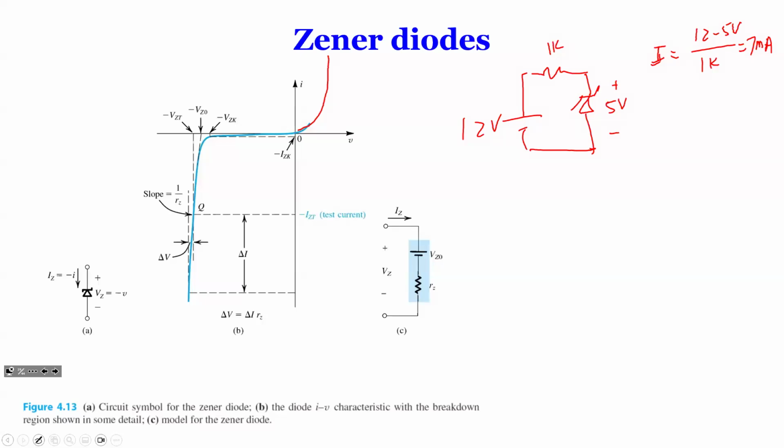As I mentioned earlier, if you look at the blue curve down below this X, it's not exactly constant. It actually changes when current increases. But again, for most cases, you can think of the Zener diode as a constant voltage drop. So now, if we change the circuit, I'm going to give you 3 examples so you guys know what happens with the Zener diode.